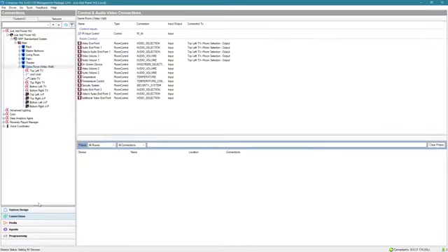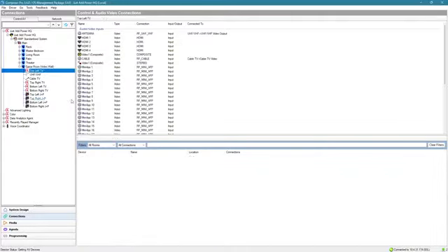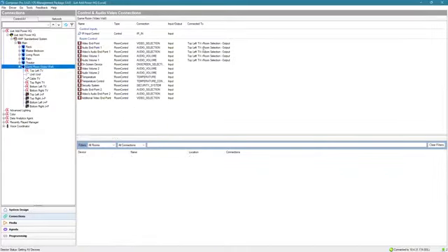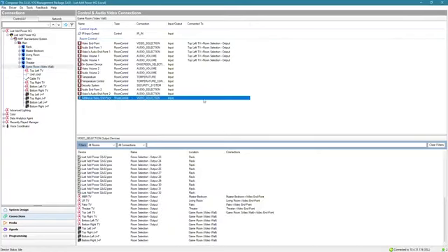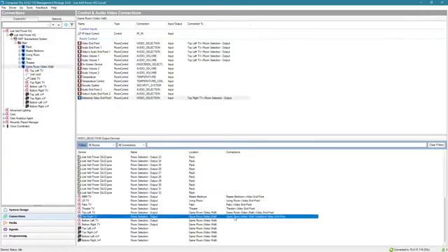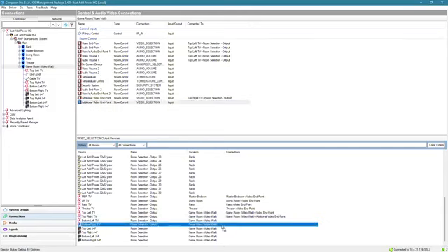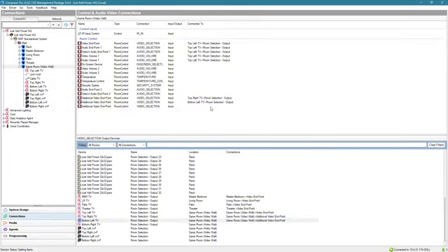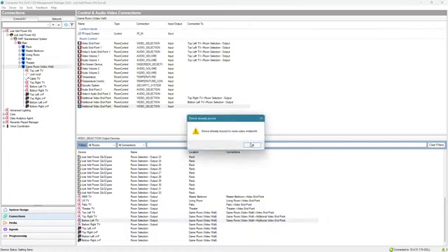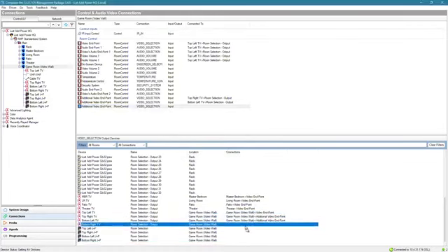So if we select connections and we go to this game room, we'll see that the top left TV, or essentially the first driver we loaded, is our video endpoint for the room. But there are additional video endpoints in this room. So we're going to go down to all of the other TVs, and we're going to add additional video endpoints. Notice that we're connecting them to the TV drivers, not to the Just Add Power drivers at this point, because the control is of the TV for power on and off, and this is important for being able to manage power for these. So you need to add the TV drivers.